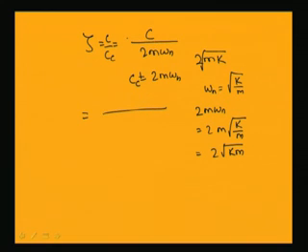c already given, this is equal to 10 Newton second per meter, and 2 into 50 into omega n equal to 10. So, this gives rise to 0.01. So, the damping ratio equal to 0.01 and the natural frequency of the system equal to 10 radian per second.